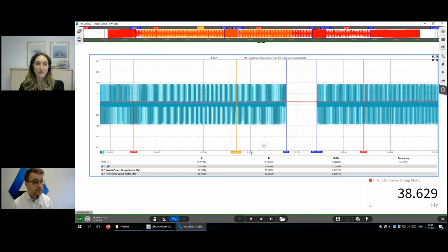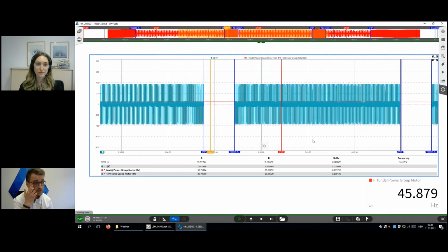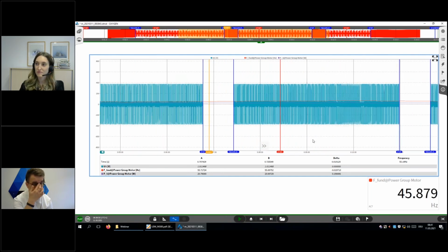It's very important, because the pre-time we set up to 1 second, but it's possible up to 10 seconds. We should mention that as well, because even if the trigger happens because of the voltage dropping or whatever, the actual incident could have happened a couple of seconds prior, and you would like to see what happened prior to the real trigger. It's very nice to have raw data recorded even 10 seconds prior to the trigger you set. In a lot of cases, this is very necessary to have.